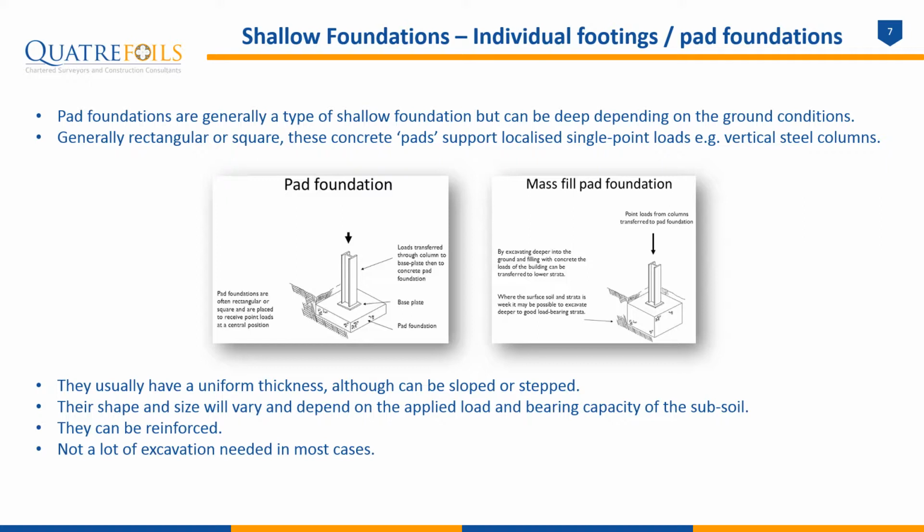Well, they usually have a uniform thickness, although like trench foundations they can be stepped. However, because of their size and focus on a particular area where load is imposed, stepping of pad foundations is uncommon. The size of the pad foundation will depend upon the load and the ground conditions. They can also be reinforced, commonly with galvanised steel bars or a mesh reinforcement. Because of their size, there's usually less spoil and ground to excavate.